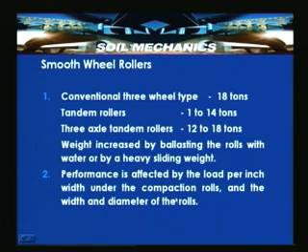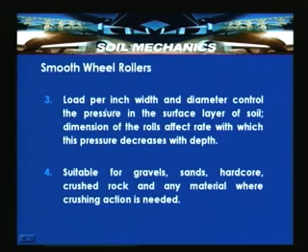The third point is that load per inch width and diameter control the pressure in the surface layer of soil. The dimensions of the rolls affect the rate at which the pressure decreases with depth. They are suitable for gravels, sands, hard core crushed rock and any material where crushing action is needed. So, smooth wheel rollers are suitable for gravels, sandy soils and hard core crushed rock where some extent of crushing is required, and then this technique becomes handy.